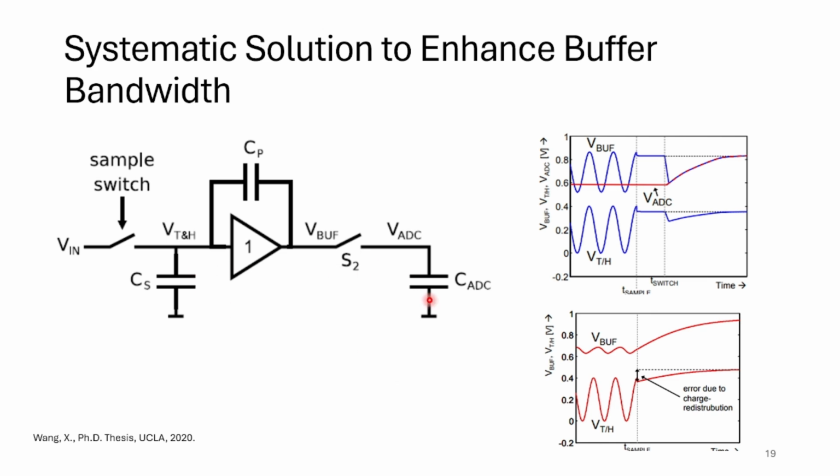Also, you can make the buffer more ideal by removing the effect of the ADC on the buffer using a switch, which you can call a buffer switch. Here, in this thesis and the related paper, they explained how with a buffer you have a better settling time. However, without a buffer, by buffer I mean a switch buffer, you have a very bad settling time in your system.